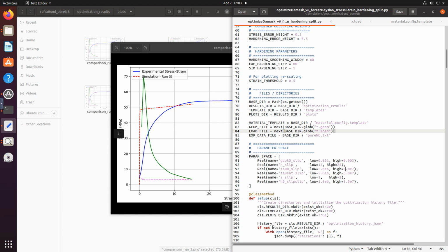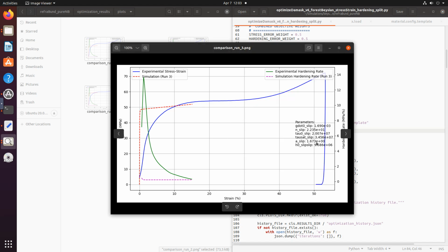So see if, for example, in these parameters you are hitting a window on the positive side or on the negative side. That means the optimization tried to find a solution here, could not, and came back. Try to increase that window in that direction and see if it can find parameters there. You will see it is still not fully automatic. You will still need to define its boundaries and adjust certain parameters, but it does the job pretty well later.